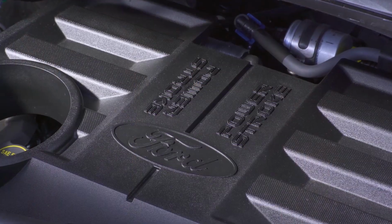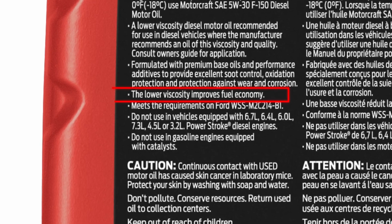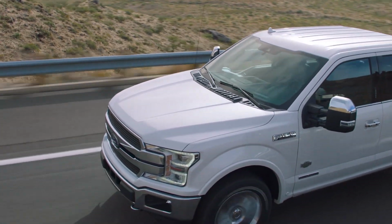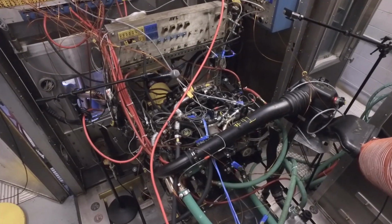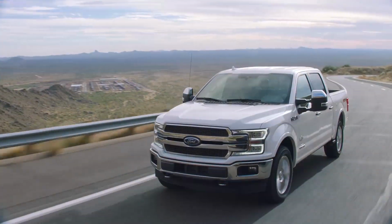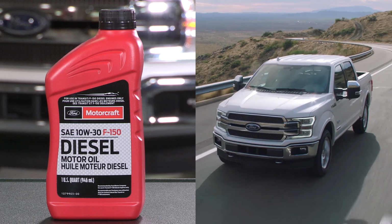The 3-liter version of the Power-Stroke diesel engine was designed to use a lower viscosity oil. That's part of what helps it support energy efficiency. Industry and Ford testing have shown that lowering an oil's dynamic viscosity can help improve fuel consumption, as long as the engine is designed for that viscosity.